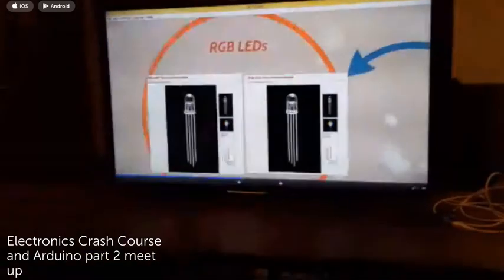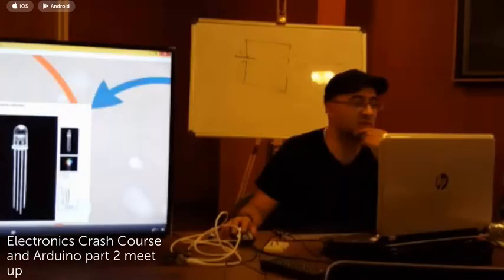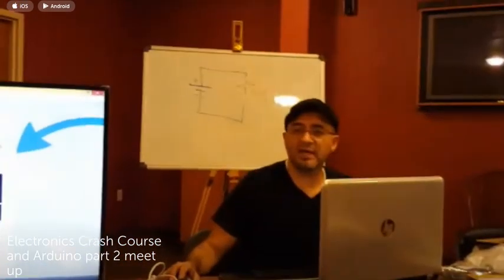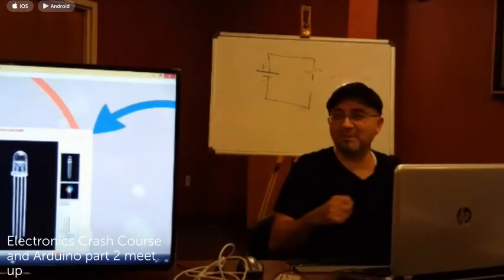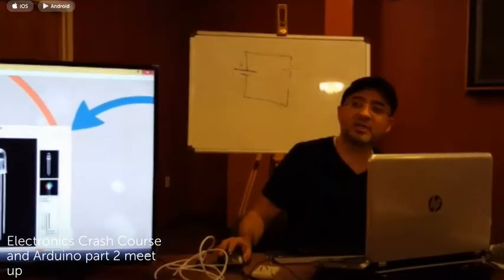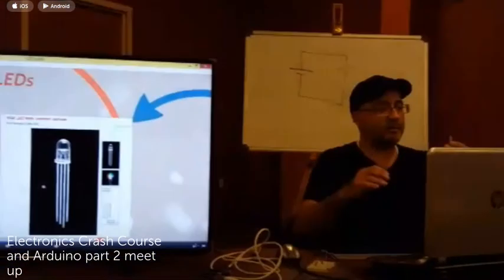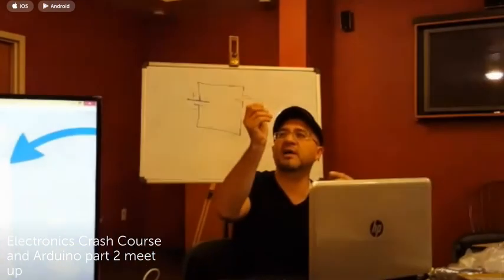Very nice. I have a question. How can you tell which one you have by just looking at it? Well, it's hard to tell them by just the look. You got to look at the spec sheet when you bought it, and if you have it, you can just test it out. Put a resistor and see how it lights up. Once you know how it lights up, then you'll say, oh, okay, I have a common anode or a common cathode. There's not a little C or an A, but if you look inside, you can see how the pins are. But this one is